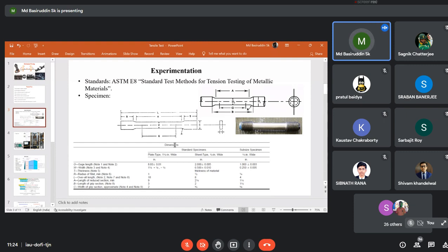Can you please give an example where the surface defects actually hampered the mechanical properties of a material? Endurance limit, sir. So for the endurance limit, a surface finish factor is included in the corrected endurance limit. Very good. One of you said the surface notch. If the surface notch is quite large and significant, and visible, then it will affect the tensile properties also.